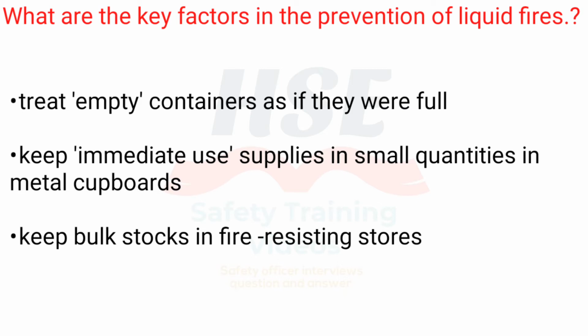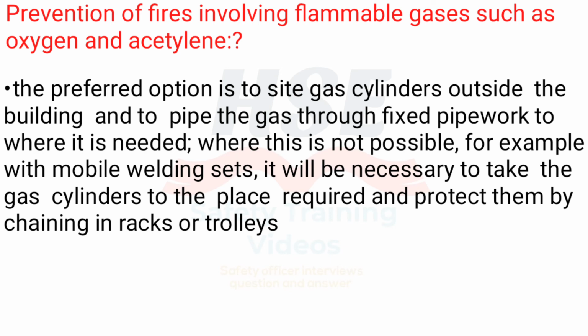Keep immediate use supplies in small quantities in metal cupboards. Keep bulk stocks in fire-resisting stores. Prevention of fires involving flammable gases such as oxygen and acetylene.